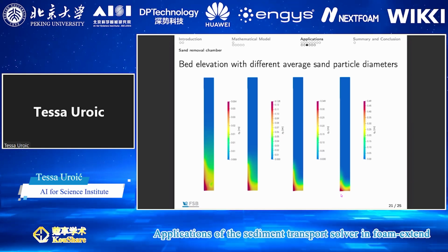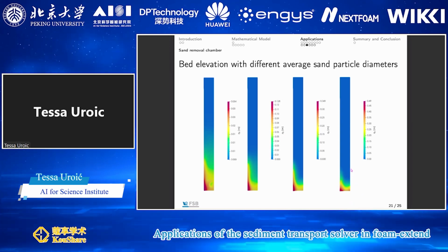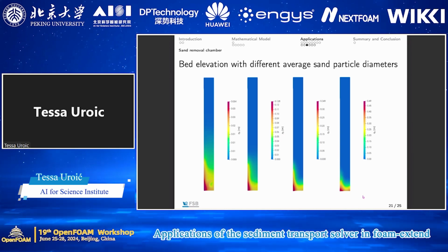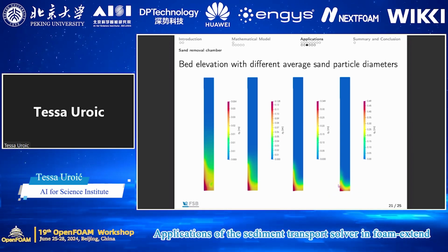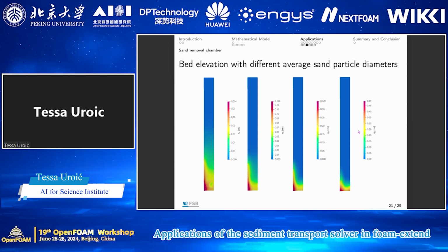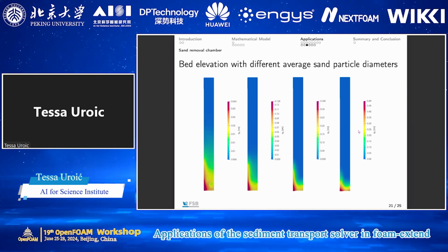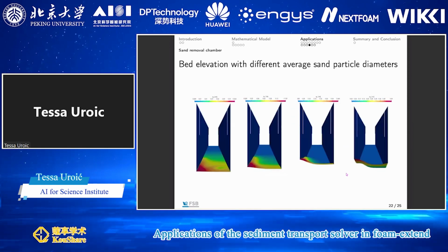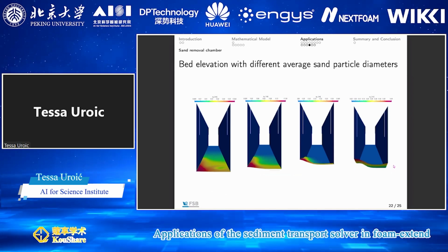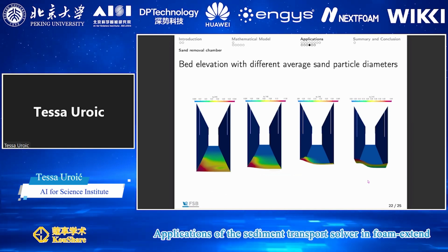And you can see that in the elevation values, since more of the sediment has deposited in the case of the heaviest, the largest particles, which is expected. So for our colleagues, this meant that they could have a descender which is slightly shorter for such cases with large particle diameters. The same picture in 3D. You can see here how the bed is quite high in the case of large particles in the first part of the descender, in the first chamber.